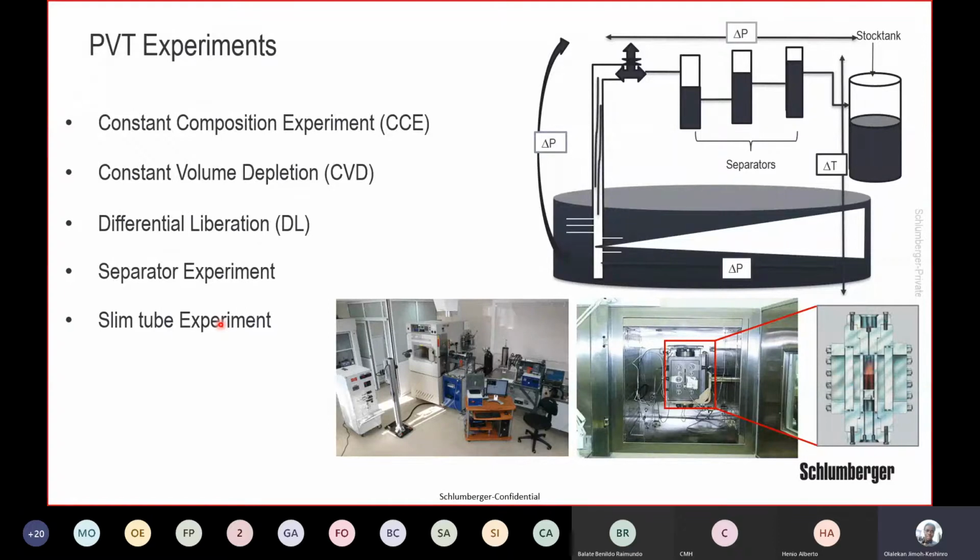So these are the various experiments that are carried out in the laboratory just to be able to see how the reservoir fluids will behave throughout the history of depletion of the reservoir, and sometimes even to know what will be the nature of this fluid when the conditions in the separator change. And that way we are able to impose all of this on the simulator to see how the fluid actually behaves when the reservoir goes through the pressure gradient and the temperature gradient.